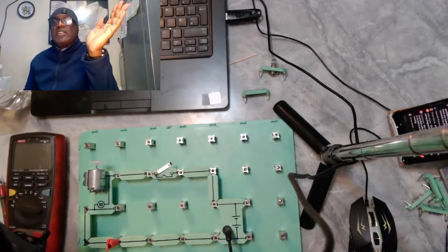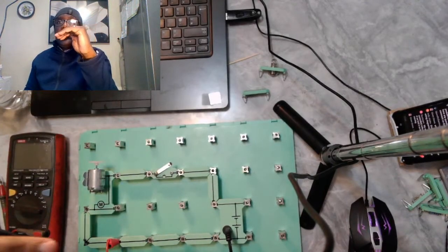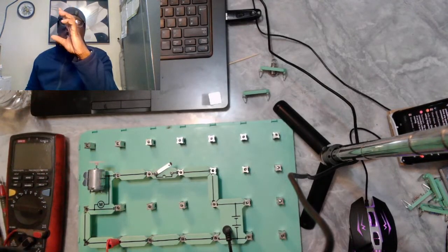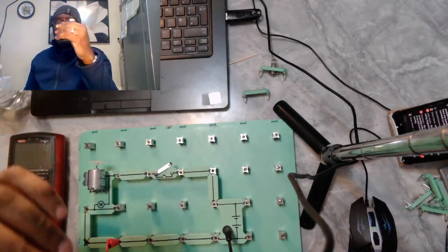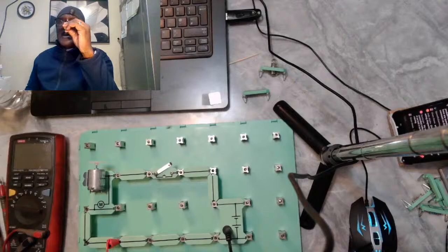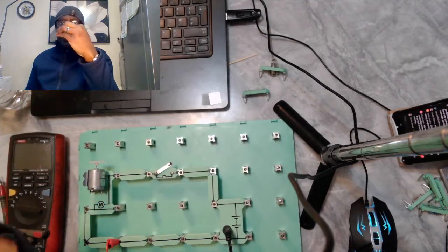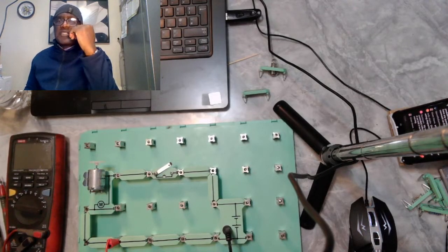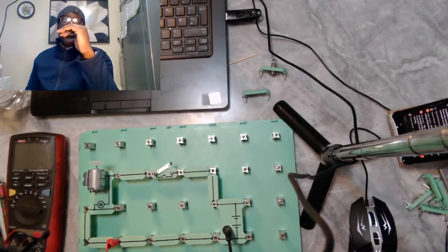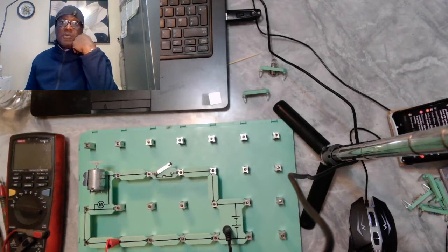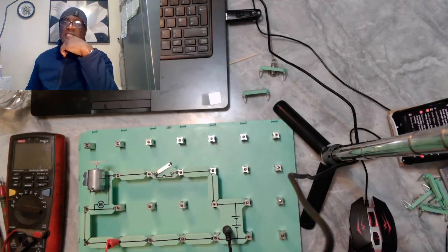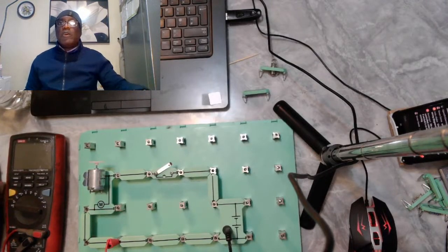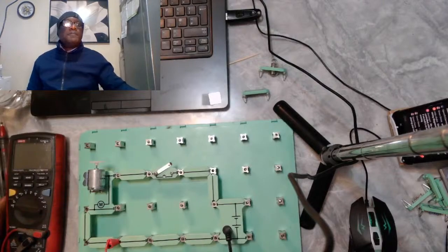So you have failed already. Whatever you are doing, you have started wrong there. So be careful what meter you use. Try not to buy the 10-pound or 12-pound meters. Try and go and read the spec first and get the right meter. It will pull you out of the hole. It will help you with electronics. Most of the sensors, whenever the ignition key is on, they do give out a voltage of about 0.5. So watch out for that one. That's why I am saying be careful. All right. Hopefully that will help someone who was thinking of buying a meter.